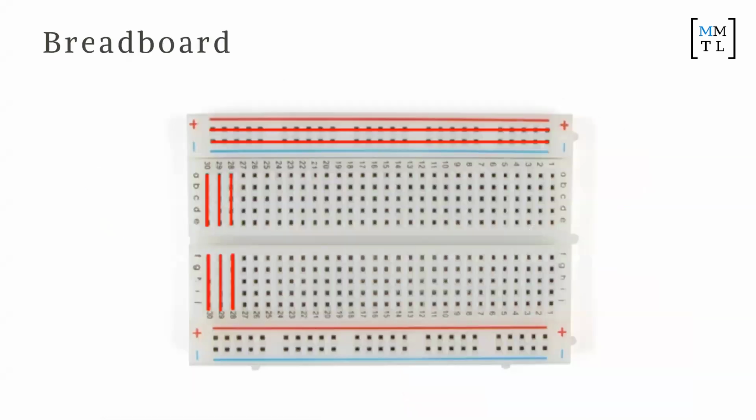All right, now this is a breadboard, okay? So you have to become a little bit familiar with how breadboards work. How they work is that there is a continuous line along the edges there, okay? So it's longitudinal, if that makes sense. So it runs all the way from one end of the board to the other end, okay? And that's true for this plus and this minus.